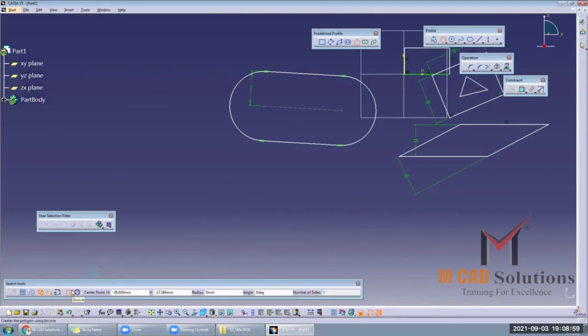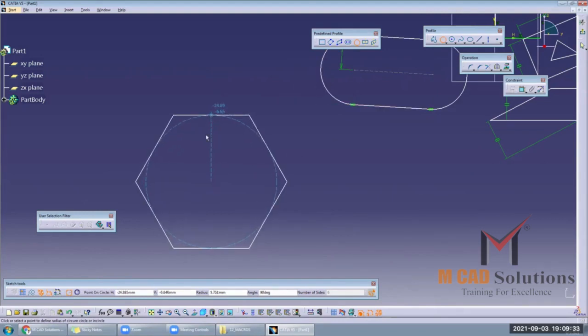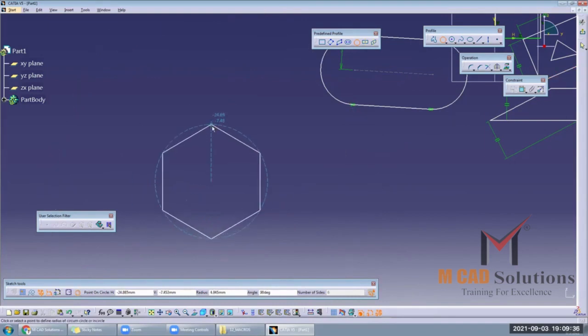So there are two methods. At the time of engineering first year, we created the different pentagon, hexagon, septagon using different methods. We take some dimension in our compass and mark it onto the circle. The concept is the same, but here we don't mark that. The software will do all the activities, but the input is given as circle or circumcircle, as per the requirement. This is the center point of the circle. The incircle will create tangency to each side. The circumcircle will pass through the vertices of the polygon, any polygon.